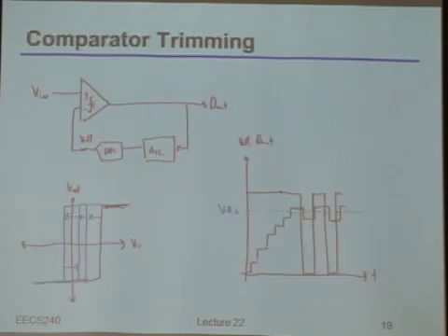So everything I've drawn here is assuming that what I really wanted to find was the 0 point. Let's say I wanted to find a different point, for example, some 300 millivolts. You guys tell me, how would you do that? Yeah, you just set V in to be 300 millivolts and you run this exact same loop. Because the comparator doesn't really care. It just says, are you above or below whatever the input actually is? So indeed, if you wanted to offset, quote unquote, cancel at a different threshold, you just apply that threshold at the input, you run this whole loop, and guess what? You'll find exactly that point.